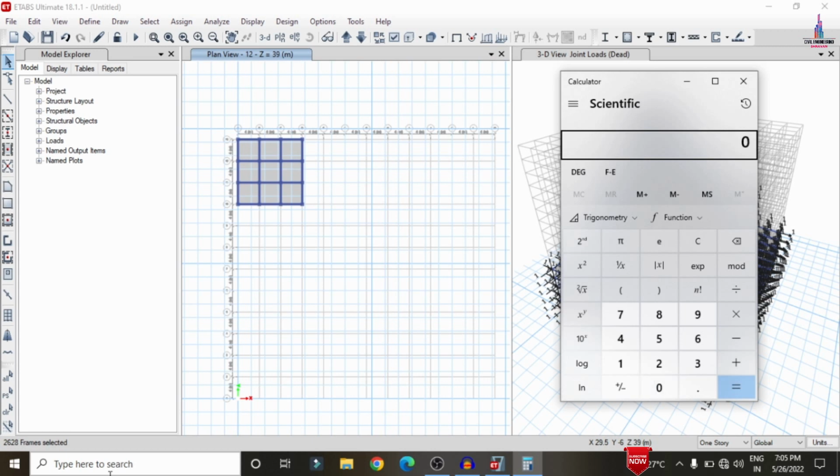Again we have to calculate the internal wall section: 0.125 multiplied by 3 multiplied by 20, so that we get the value 7.5. Again in the same process for the parapet wall loading condition, 0.15 multiplied by 1.2 multiplied by 20, so that we get the value 3 here. So 3 plus 7.5 plus 13.8 gives the value of 24.3 kilonewton per meter for the wall loading condition system.